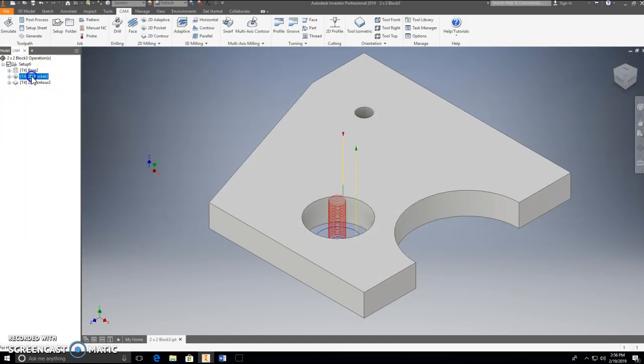It's going to go all the way through, spiraling down. That's fine. For your pocket, again, it's going to spiral all the way down to the bottom, and then do your cut around. And again, honestly, we should do 2 passes for this. Now, I thought about that because it's still going to be cutting a 1/4 inch thick, and that's probably a little bit too much. So we are going to modify your pocket. To do that, we're going to double click on it.